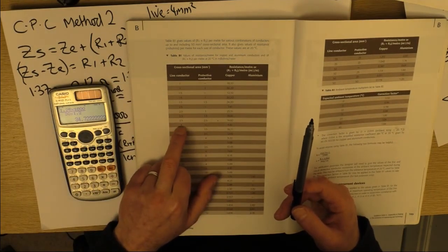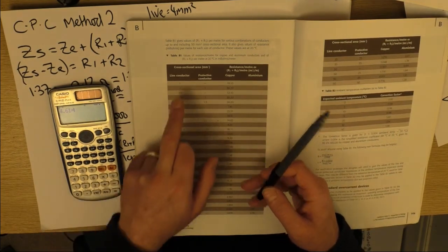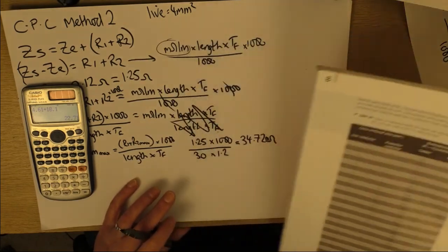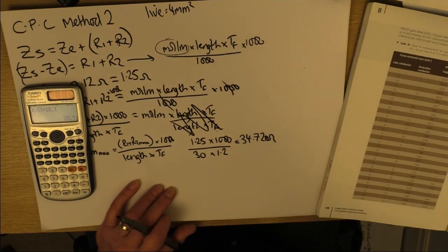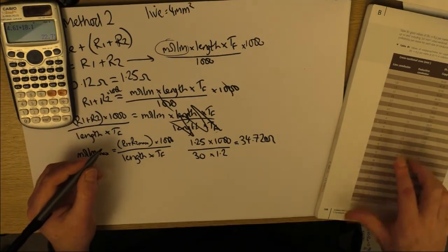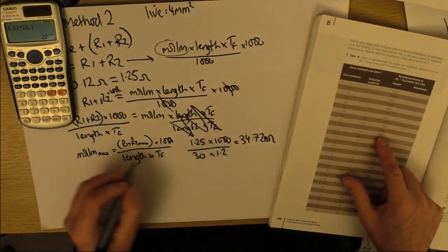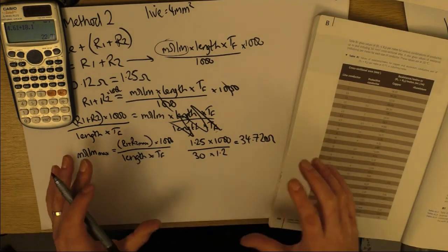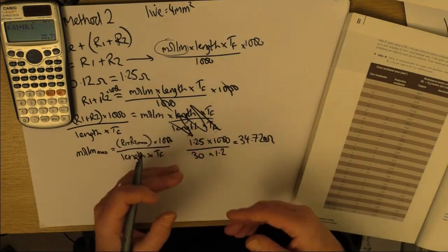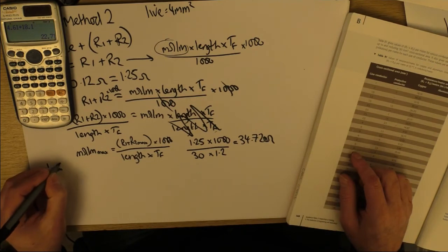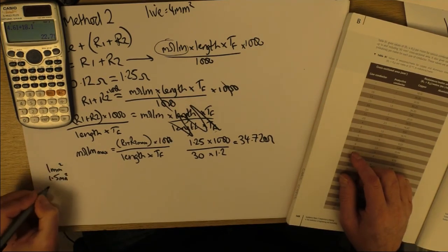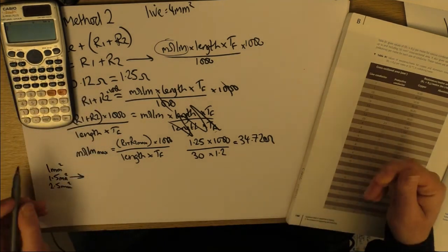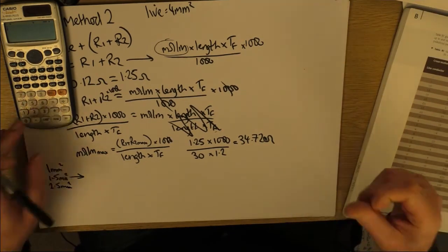We could check the 1 mil, so 4 mil on its own is 4.61, 1 mil on its own is 18.1, and add them two up, it comes to 22, so that would work as well. I think 1 mil is probably a bit too small mechanically, it might get bashed about a bit. So we could select 1.5. That makes sense. So 16.71, that gives us a value, and we'll need that in a minute because we need to calculate our actual ZS before we use the adiabatic with this method. But that's how we could choose a CPC using it in a different kind of way. So at the moment we're saying 1 mil would work, 1.5 would work, 2.5, all of them would work really. I think I'm going to go for 1.5, but as I said, value engineering and all that jazz, you'd probably get shot if you went for 1.5, so be careful.